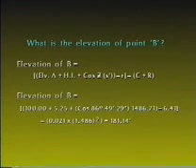The elevation of B is equal to the elevation of A, 100 feet, plus the HI of the instrument, 5.25 feet, plus the cosine of the zenith angle, 86 degrees, 49 minutes, 29 seconds, times the slope distance of 1,486.71 feet, minus the HI of the prism, 6.41 feet, and then minus the correction for curvature and refraction, 0.021 times 1.486 squared, to equal 181.14 feet for point B.